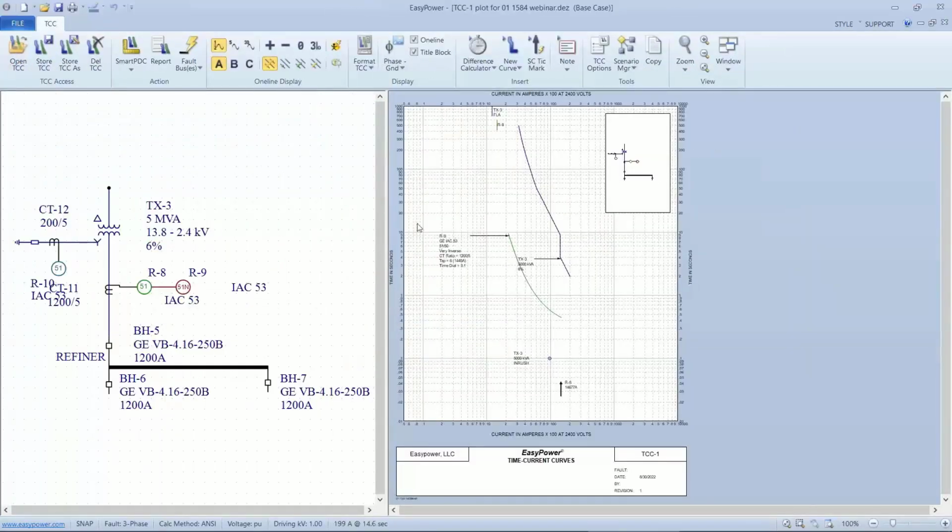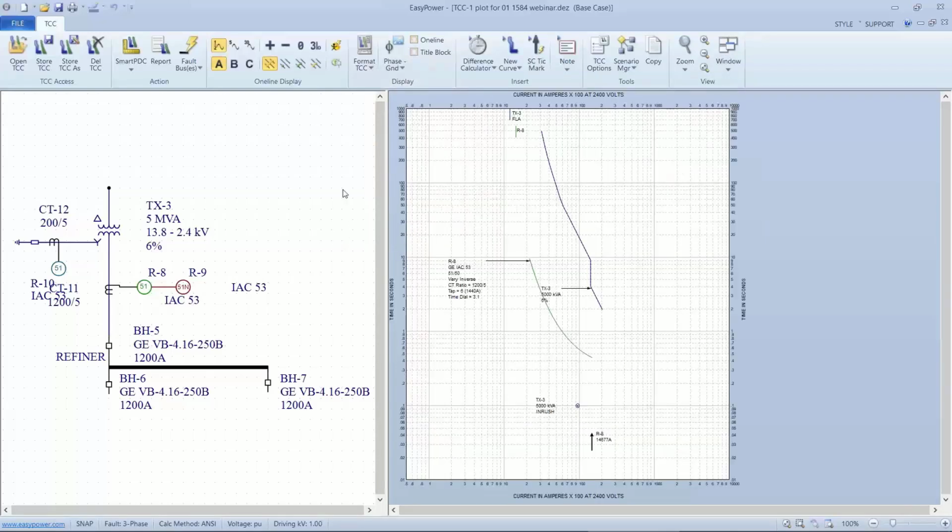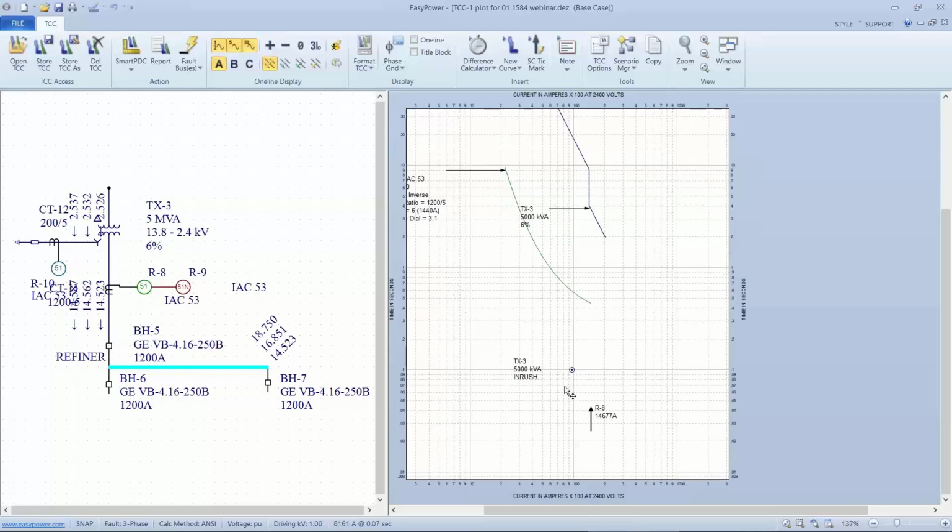Again, this is just what I do to make sure I'm on the right page. If I fault this bus, I can single out just the one bus and fault it. Again, I'm faulting at a half-cycle current, a 5-cycle current, or a 30-cycle current. Does that really help the equation? Well, it's changing slightly over all three ranges, but what I'm really concerned about is what's going on with the relay itself.